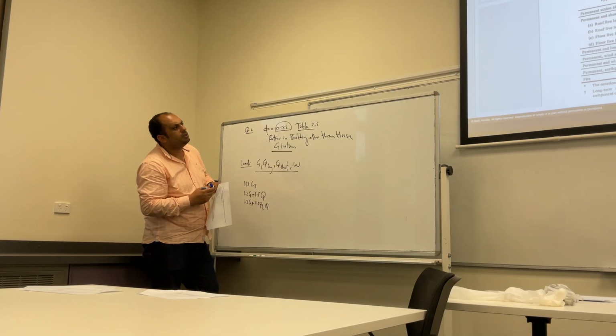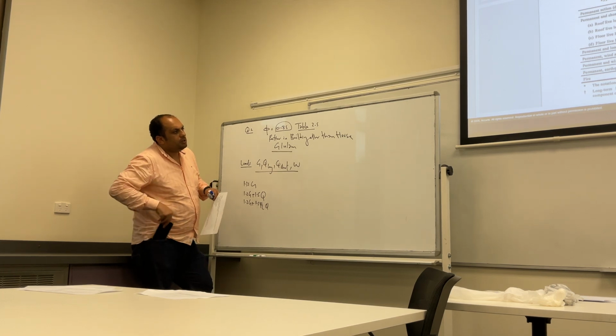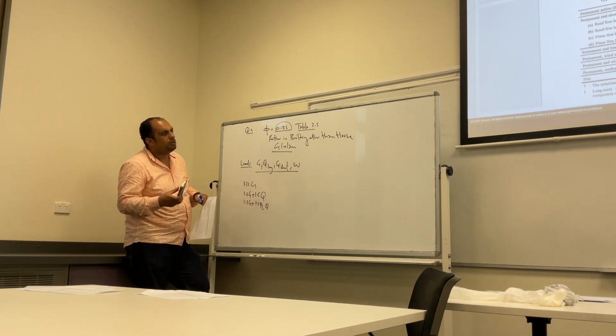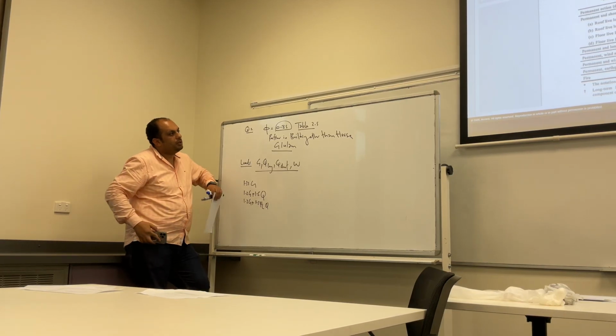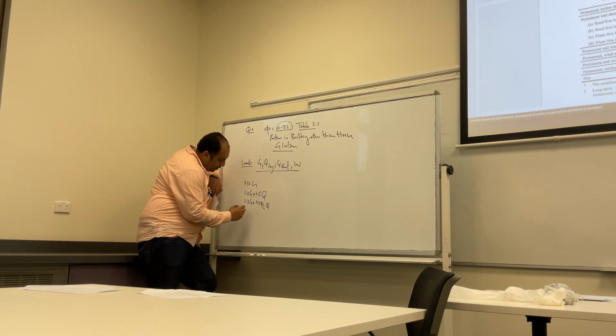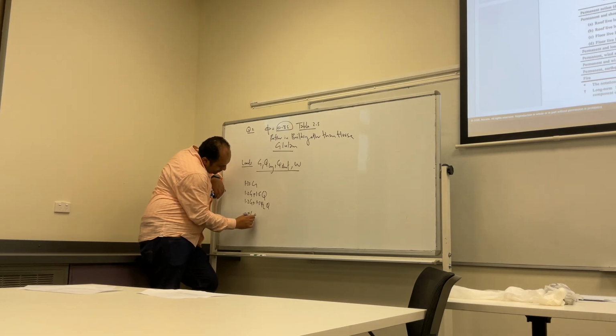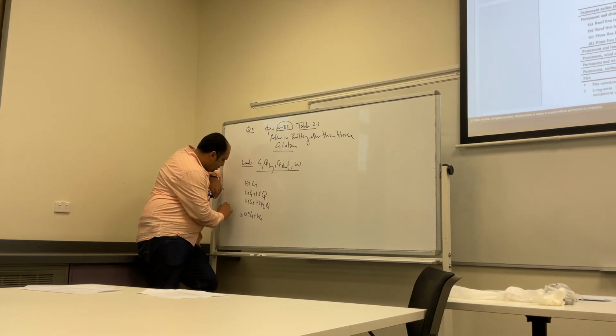Are we doing the 1.2 G plus wind plus psi C Q? Yeah. We don't have that. We have uplift wind, right? Yeah. So we have the fifth one, not the fourth one: 0.9 G plus W. Why? Because he mentioned that the wind is uplift.